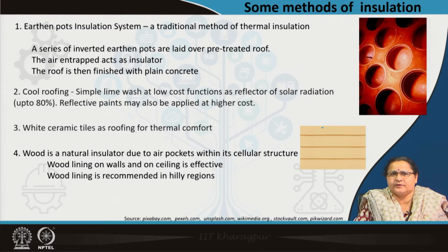So, wood can act as a very good insulator. Wood lining on walls, inside walls, on ceilings, particularly in hilly regions where it is abundant, gives you thermal comfort inside. Whatever your building material, it may be concrete, it may be stone even, because stone is also abundantly available in hilly areas, you can put wood lining, or the building itself may be made of wood logs.